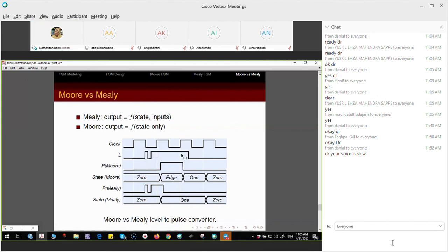And then steady. There is some jittering in the beginning here, so nothing happened here. Somebody pressed a button. If it's a push button, maybe normally off. Initially the button is 0, you press, but the process takes 2 plus 2 pulses before it's steady. So for the Moore finite state machine, here it doesn't detect, right? And the state is still 0.